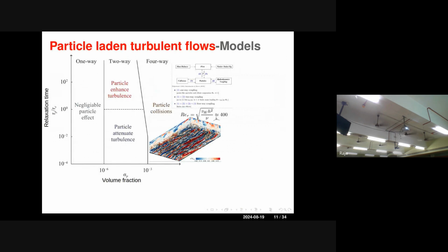The other way to pretend is to do wall-bounded turbulence, meaning there will be a channel and flow comes in this direction, maybe with a bulk Reynolds number of something like 13,000, 14,000, 20,000. There will always be high-speed streaks and low-speed streaks, and particles might be moving on them. So it depends on how much volume fraction of particles one uses, and whether these particles have inertia: do they immediately adjust with the flow?